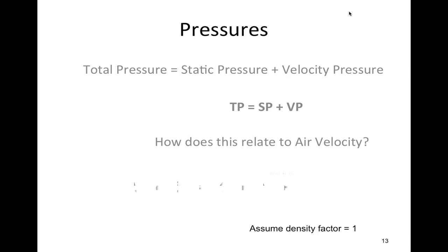If we have to correct for it, say D is 0.8, in other words, the air is only 8/10 the density of air at standard temperature and pressure, like where we're at the base camp in the Himalayas, where we have a duct. Not likely to have a duct at base camp in the Himalayas, I guess. But if you had one, then that density might be 8/10 of what it is at sea level, and we might be dealing with a very different situation for the effect of this velocity. So that's how we would use the calculation.